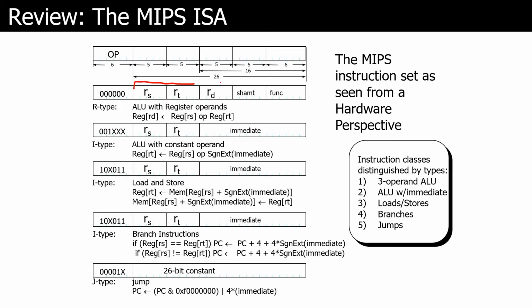The instruction ones go into the register file, and they indicate what registers we're going to look at. The shift amount will go into the ALU if we're going to end up shifting. Our opcodes tell us what control bits are going to go in, and our function further specifies those control bits. And you can see that all of this is just information that's going into the CPU. So with just 32 bits, we can do this wide array of operations, which is pretty cool.